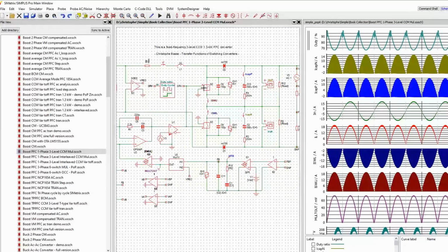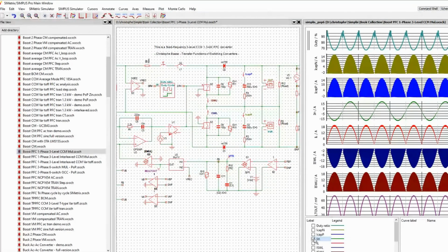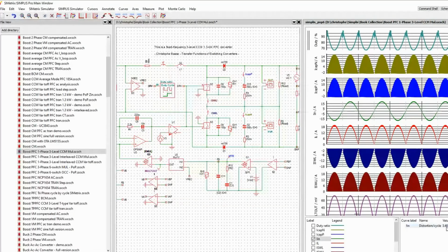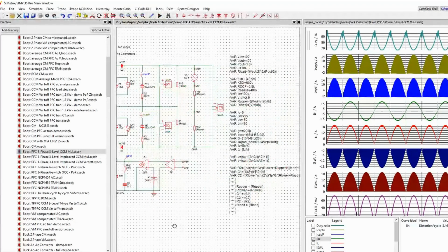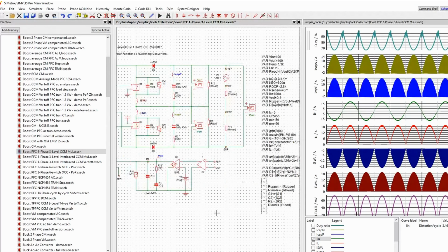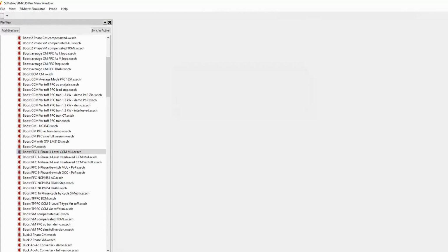And then I can look at, let's say if I do IN and press F3, I can look at the harmonic distortion of the current, and I have 3.4% as harmonic distortion. Again, it's automated. I could explore different crossover frequencies and see that if I push the crossover, then I may have more ripple coming in, and then it's going to affect the distortion. So as usual, it's a trade-off between transient response and the distortion you want to look at.